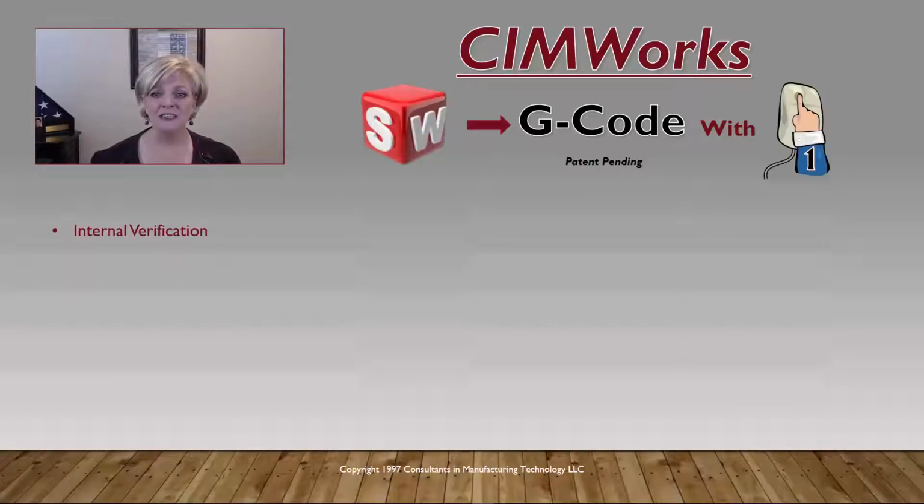Internal verification. You will have the ability to verify your parts, including wire path, automatic slug removal, and comparison with the finished part solid model. Set cutting conditions. We have fully integrated Agie Charmille's EDM Expert, and the cutting conditions can be set at both the part and the feature level.